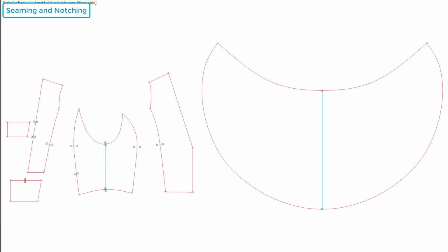This design sews the sleeve to the bodice up to partway along the armhole, allowing the flare of the sleeve to be fully showcased. The function you're viewing now lets you move the pieces around to find the perfect seam endpoint that fits your design. Once you've found it, you specify where to place the notches. Next, we'll also check if the sleeve length matches your design vision.